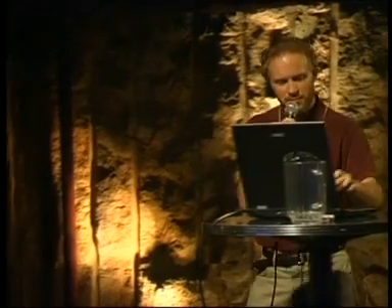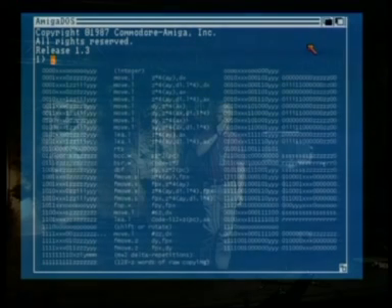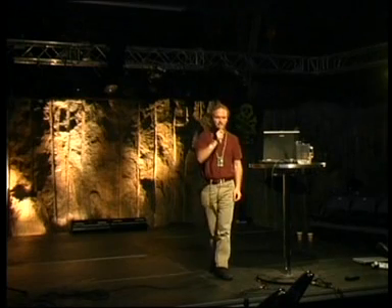So in this special instruction there's also only 8 bits for the offset, but I just shifted up 1 here, so we can jump twice as far in the same address space, and that actually makes quite a big difference, because quite often you have these loops that are larger than 128 but not larger than 256. So that saves a bit of space there.